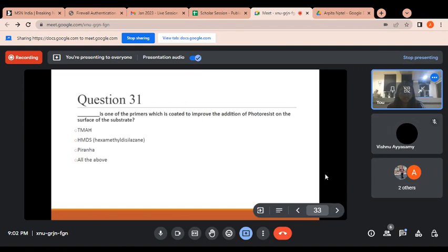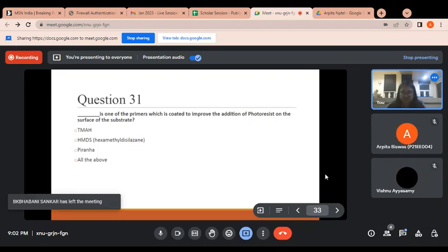Yes, ma'am. So question number 31. Dash is one of the primers which is coated to improve the adhesion of photoresist on the surface of the substrate. TMAH, HMDS, the hexamethyldisilazane, Piranha, and all of the above. So what is the right answer? Vishnu?